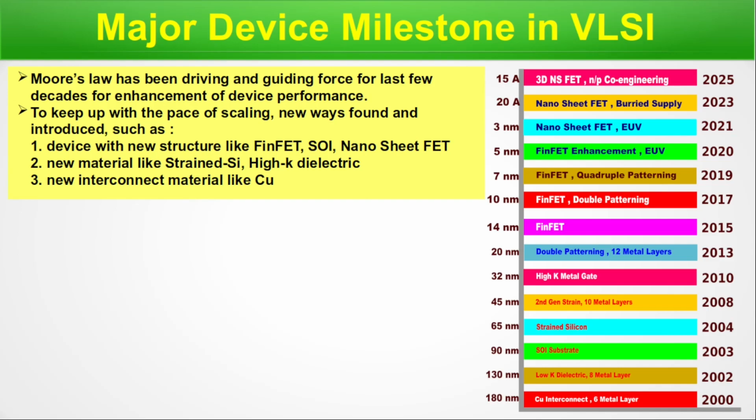We also try to understand what the requirements of High-K Dielectric are and what problems we actually face to introduce High-K Dielectric in a stable CMOS fabrication process. So today's discussion is all about that High-K Dielectric. The High-K metal gate combination was introduced in 2010.